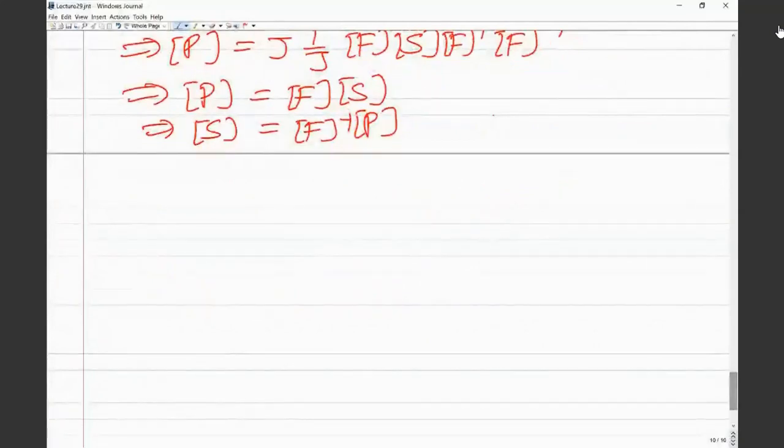So now, after having defined strain measures and different stress measures, we ultimately want to develop the element level governing equations. So let me start from the weak form. First I will write the weak form in the current configuration. That's more logical, although we can directly start from the principle of virtual work, which is more general, of course. But we need to look at how the different reference and current configurations come into the picture.